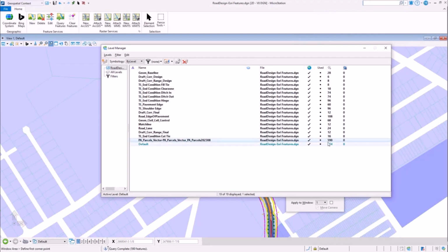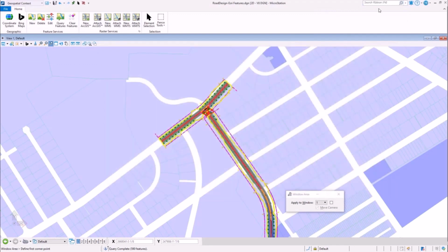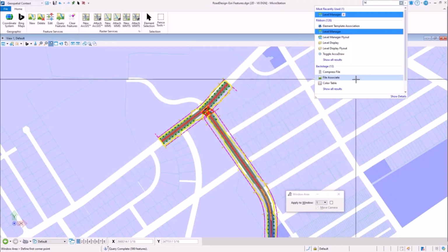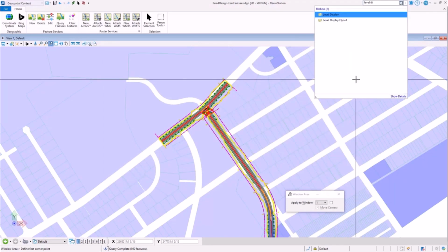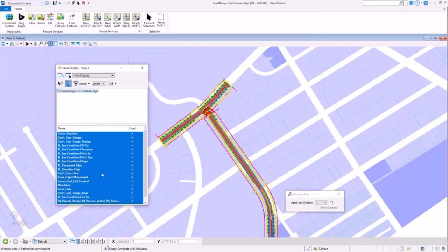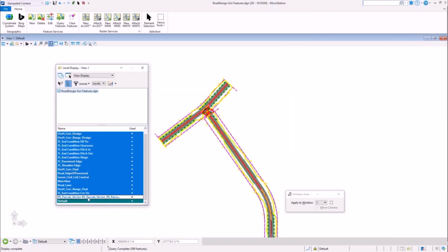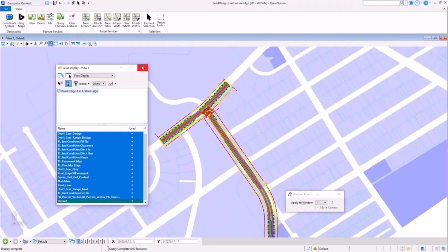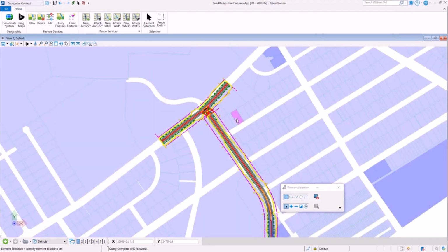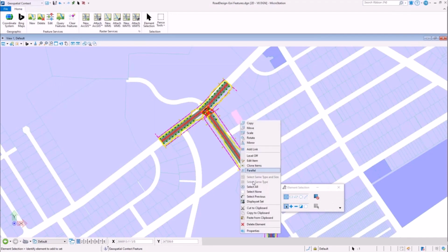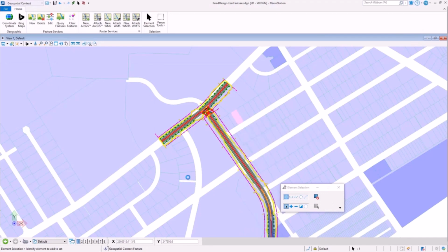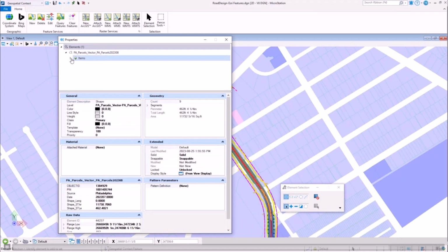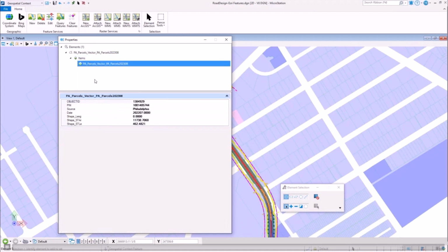When using a query feature tool, only features that overlap the extent of the active view are created. For each feature, a DGN element is created and placed on the level generated by appending the connection name and the layer name. Since the imported features have been placed on a dedicated level, it is possible to stop their display by deactivating the display of this level.